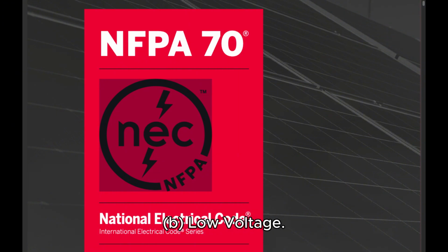(b) Low voltage. By special permission, smaller working spaces shall be permitted where all exposed live parts operate at not greater than 30 volts RMS, 42 volts peak, or 60 volts DC.